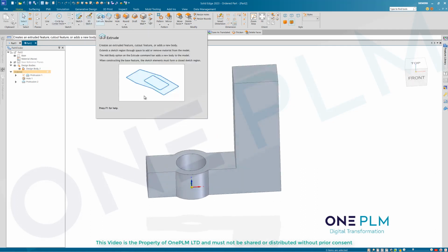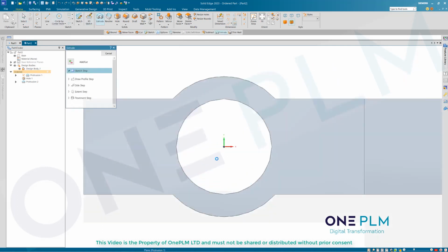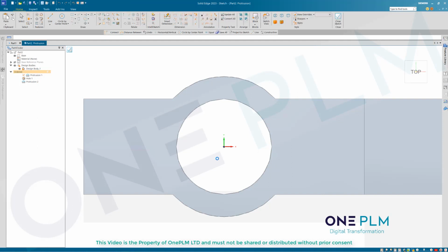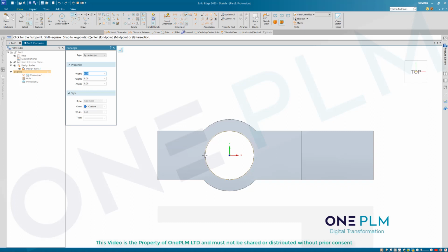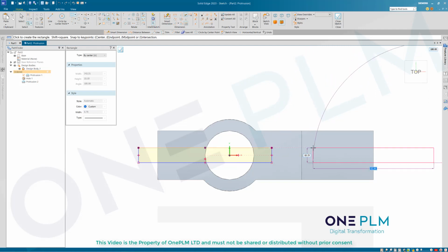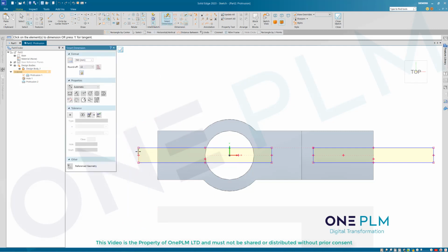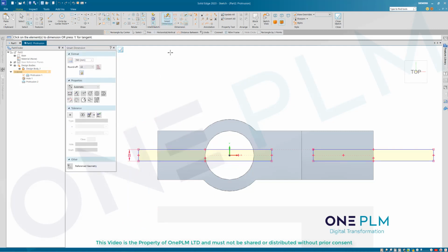So we've got the rest of those cutouts as well. I'm going to follow the same kind of stuff that I did with the Synchronous on here. I'm going to use 2 cuts on here. We can do similar items to do the same kind of thing on here. I'm going to link that to that geometry on there. Dimension these both up as, let's just make sure we get the dimension command, both up as 8mm.